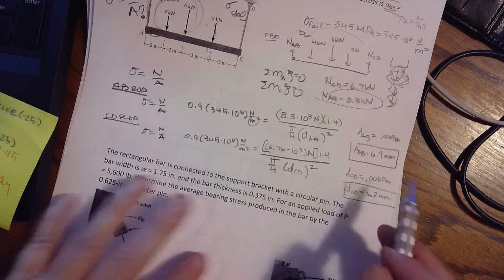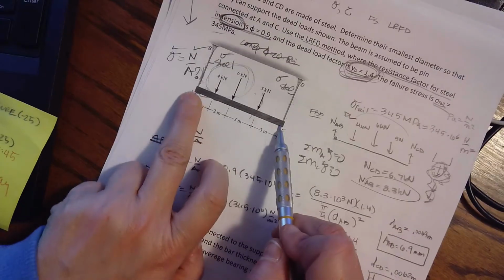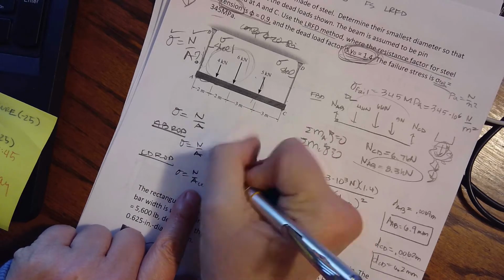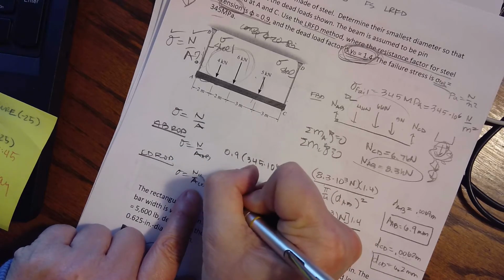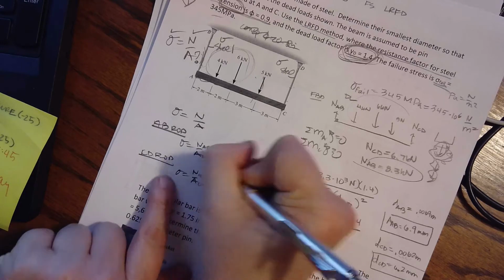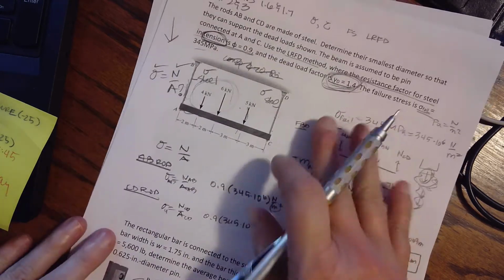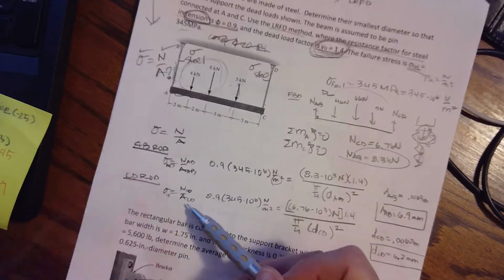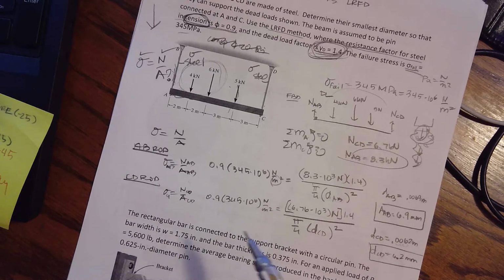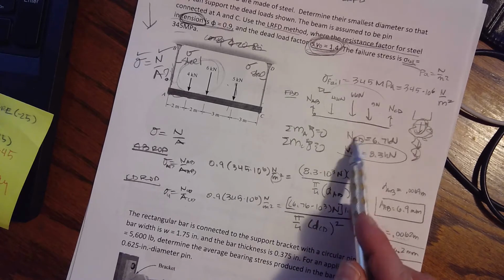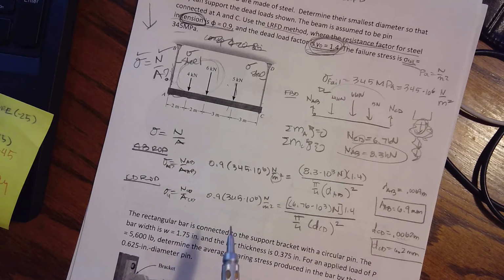So a couple of things. When you're finding these internal normal forces and you're finding areas, you really need to make sure that you're distinguishing the normal force of CD, the normal force of AB, the normal stress of AB, because you may end up with several different tie rods in a system. And they may all have different diameters. They may all have different allowable stresses if they're different materials. And so you need to keep up with making sure that you signify what you're working with. Otherwise, you could possibly end up with wrong answers.